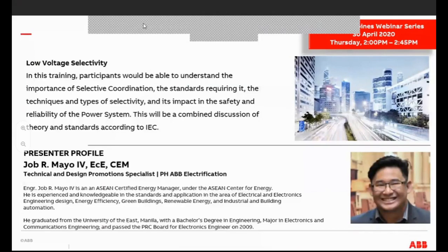Is this the question of up to what spectrum your active filter is working at? Well, for our harmonics filter, this is actually working up to the 100th harmonic. We can have that. But usually, if you have a harmonics solution, we adjust it to the 7th and 21st harmonics, and then all of the other harmonics are solved.